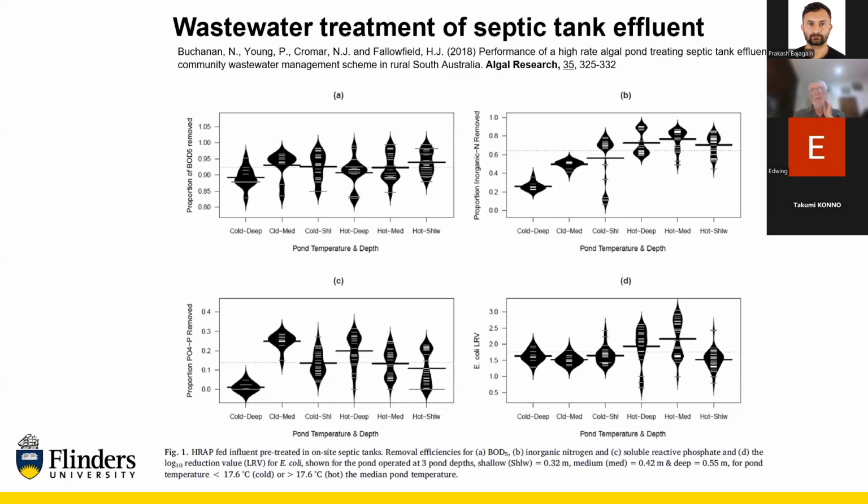When you're operating a photobioreactor and you're intentionally growing, say, a single strain of algae for producing biomass for some purpose, one of the parameters you can change is dilution rate. Dilution rate is the same as retention time. It's the rate at which you add liquid to your system.